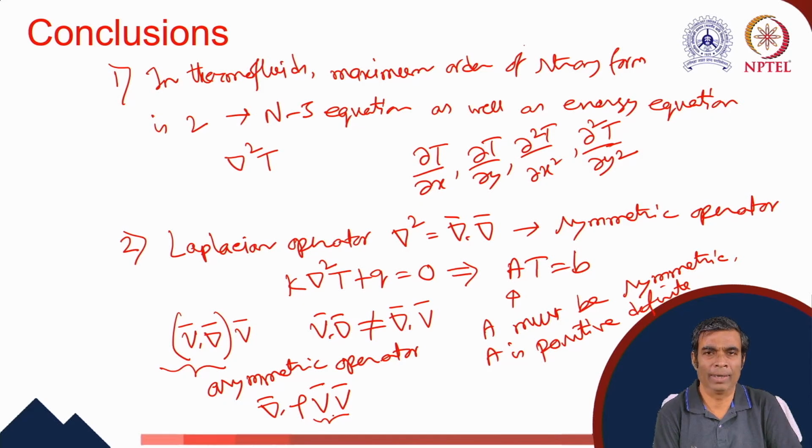When we handle these problems by using CFD treatment, one of these velocities, the first one, we treat as a coefficient or a known quantity, and the second velocity, which comes later, we treat as the unknown or the degree of freedom. So the known part acts as a coefficient, and then the equation is reduced to a linear equation, and then we can use the linear equation solvers for this.